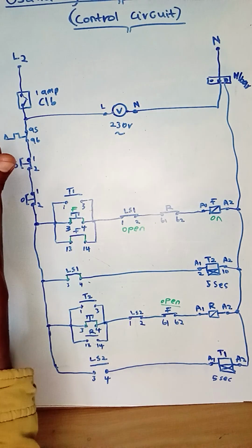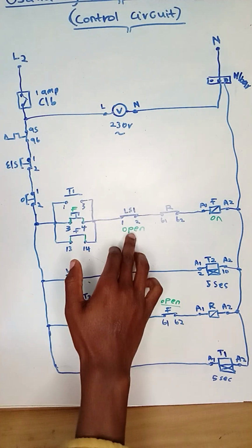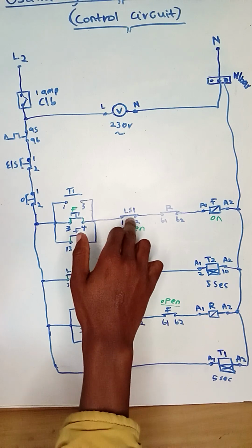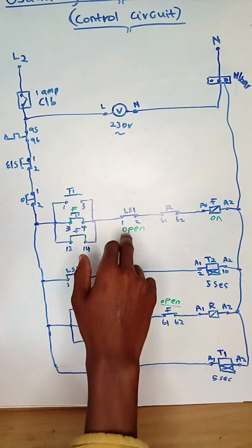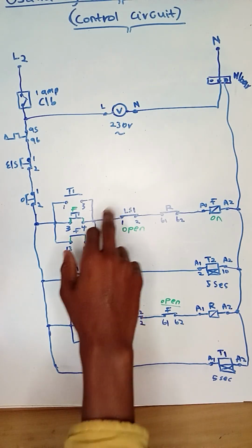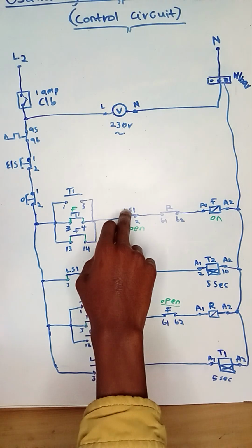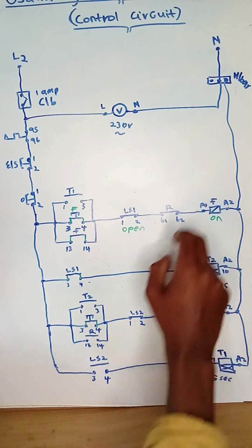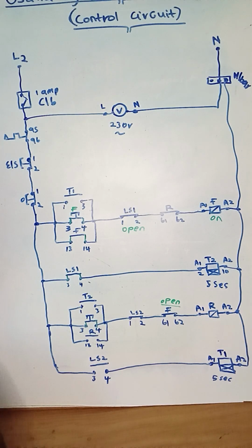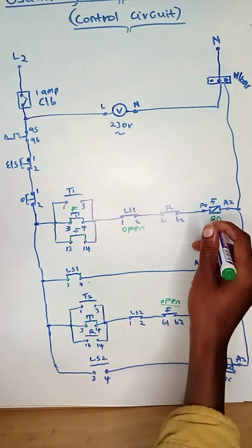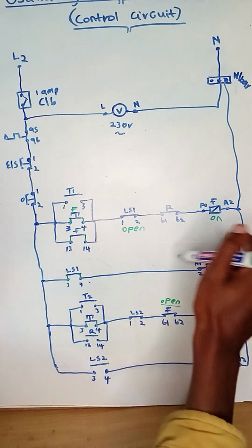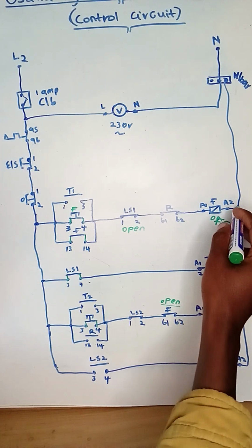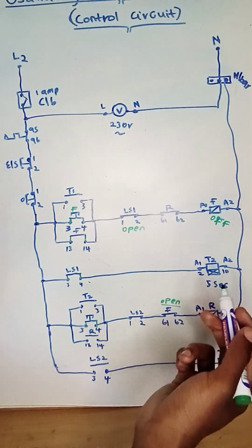Right now I'm holding my switch like this. So if this contact of limit switch 1, normally open, is open, which means right now it broke the current from the live, which means it will de-energize the coil of forward. It will de-energize the coil of forward, it will be off. The coil of forward is getting only the neutral, so it will be off.